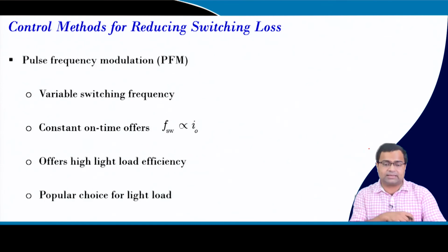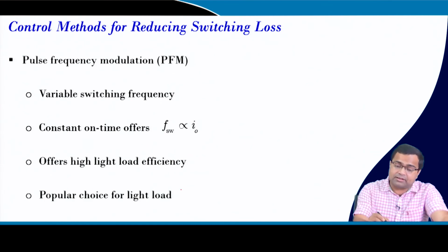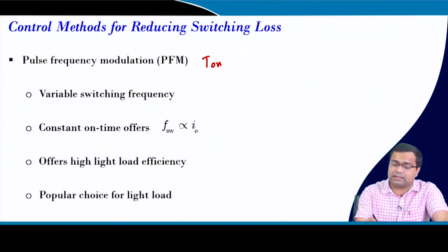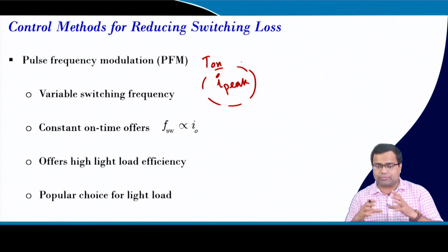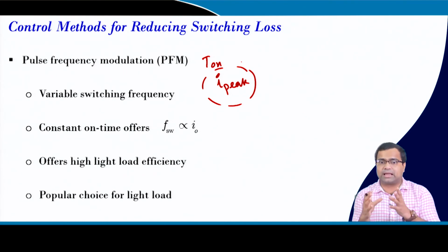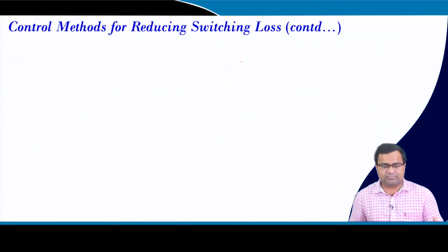very popular choice, and we have two architectures, one is purely on time set by timer, another is the on time set by peak current, and this is the most popular one because it takes care of the adaptation in the on time when the input voltage changes.